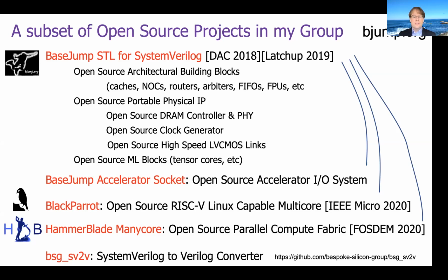In addition to the BaseJump STL project, we also have a project called BaseJump Accelerator Socket. The goal there is to handle the problem of I/O and memory system for new accelerator designs that are being prototyped in research. Basically, you can focus on designing the accelerator, and then we have a standard interface that you hook up to, which gives you essentially a packaging solution, a motherboard for your accelerator, and a PCIe connection to a Linux server with a Xeon host. The whole I/O system, the drivers, the firmware, everything has already been pre-designed for you. So you can focus just on what goes in the center of your chip and what your value add is in terms of an accelerator.